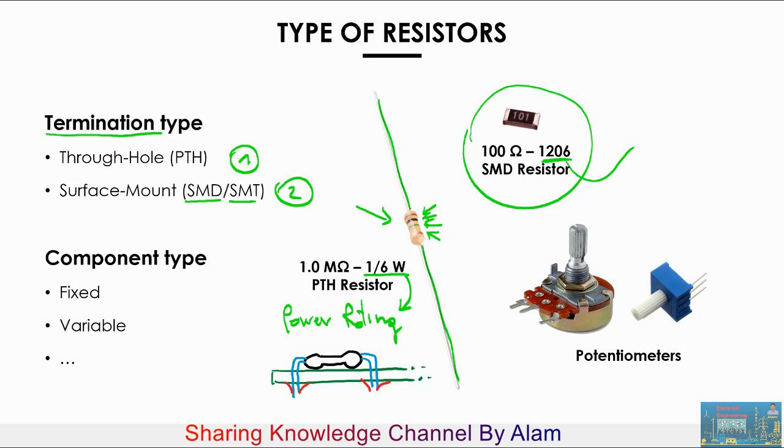So a 1206 component, if we draw it like this, is 3 by 2 by 1.6 millimeters. So just like this, 3 by 2, 1.6, and these are millimeters. And this is one of the biggest dimensions for SMD components. You can go all the way to the package that is 01005, and in this case the dimensions are 0.2 by 0.4 millimeters.